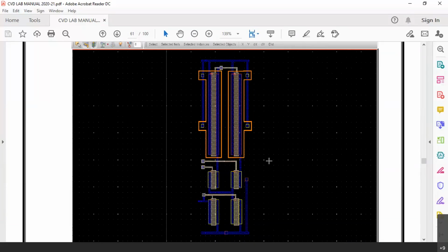So in general, in the industry they perform a back annotation process. Means after the layout is over, they will simulate it once again and they will find out the specifications after the layout. That is going to be the final specifications for the chip. If there are deviations, again they will have to work out on the circuit simulation once again to improvise on the performance.